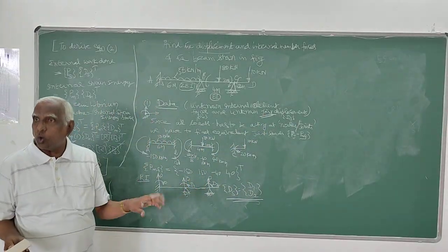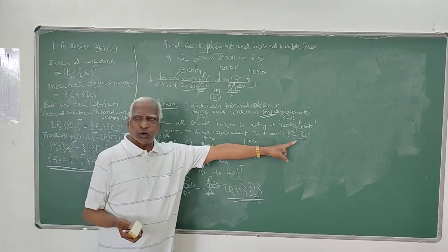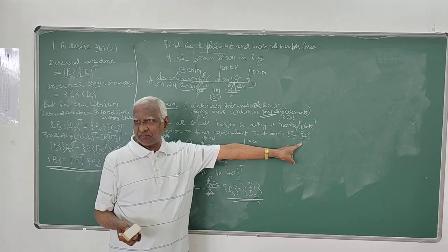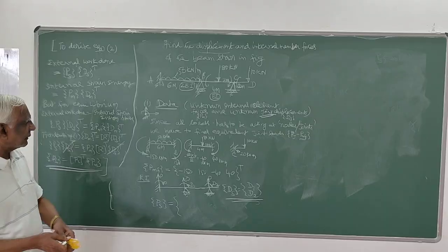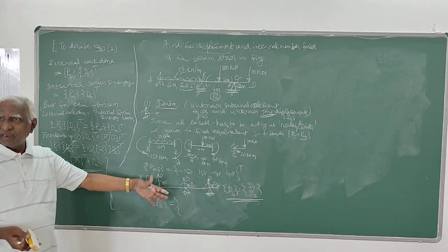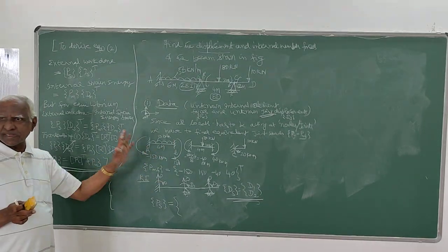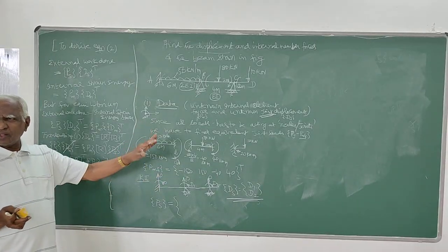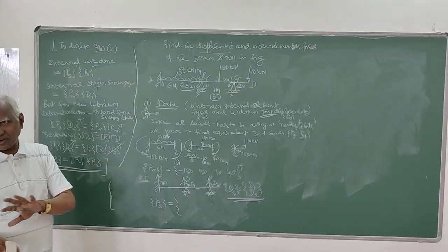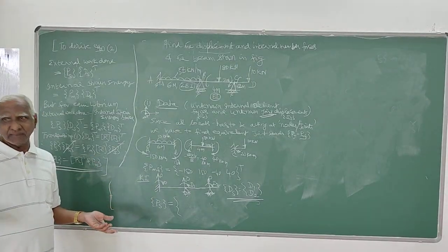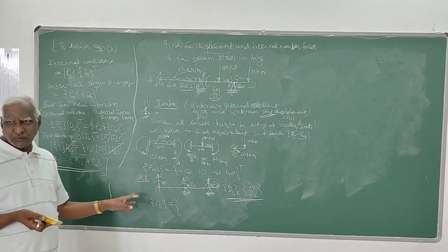And the corresponding external loads corresponding to these kinematic indeterminacies, that is nothing but Ps. Correct? I told you Ps is nothing but Pj minus PMS. This corresponding Ps you can also work out here because these are all known quantities, known from the data given. That's why I told you the first step is very, very important. You have to identify the nodes, identify the joints, mark all the nodal coordinates, and of course all those details you have to do in finite element analysis. In the classical method, only this much is required, because we are not generating the stiffness matrix using the general stiffness matrix as in finite element. Here we calculate and do it in the classical method.